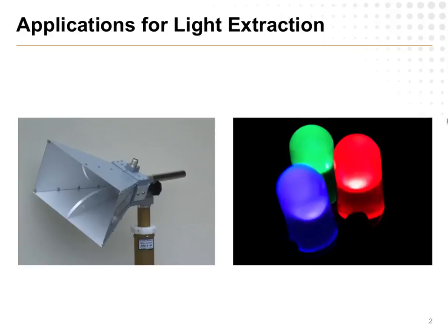I know in some processes you cut a little square and you need a little space where the saw will physically go in and cut them apart. But 6 inches or so, you can pack many tens of thousands of chips on that in principle. And then when you do a batch of 5 of them together, there are more tens of thousands. So you can easily get somewhere like a couple 100,000 chips off of a single process run.